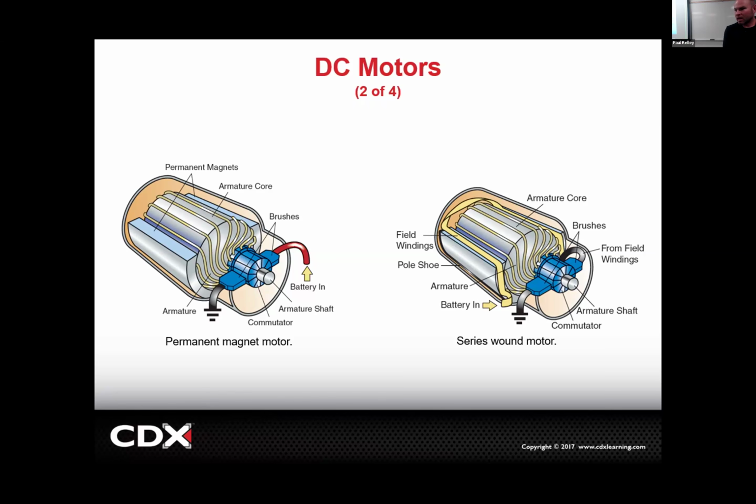But then when you bang on it, if you can just get it to rock just a little bit, it'll get within the magnetic field to be strong enough, it'll pull the motor over. And once it starts to spin, the 7 working segments will coast across the 1 bad one. But once in a while, the 1 bad one will stop where you really needed it not to stop, and then it won't work, right? So that was kind of like the visual way to understand what might happen.